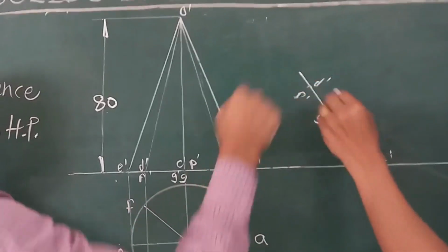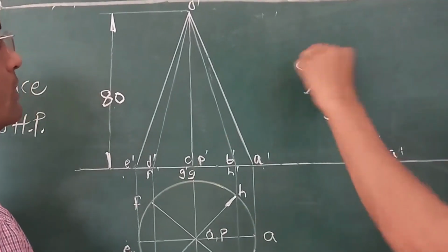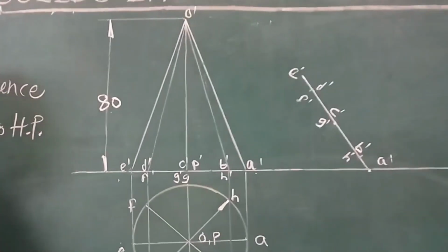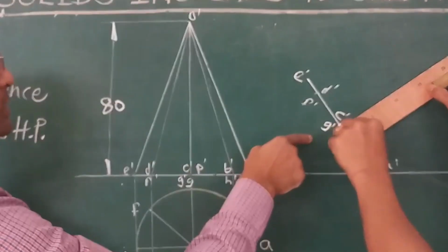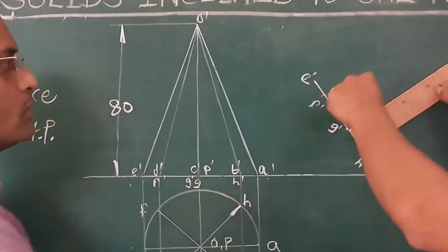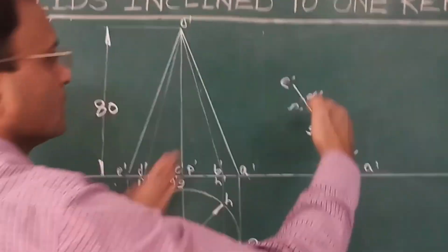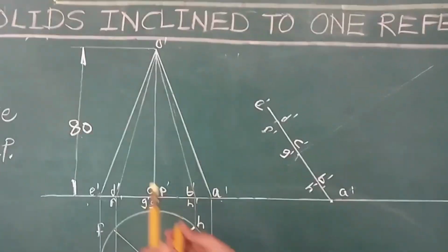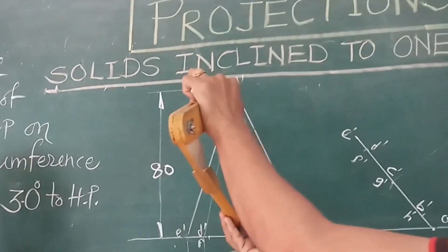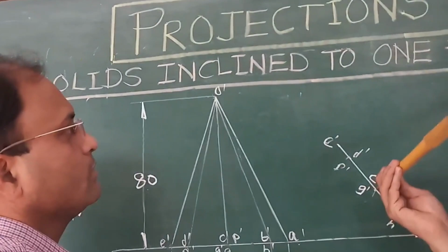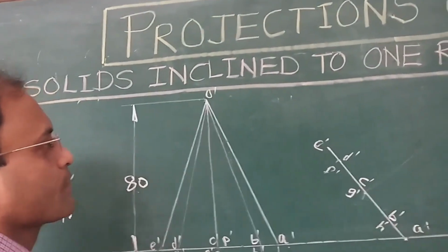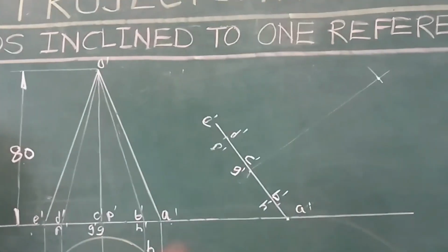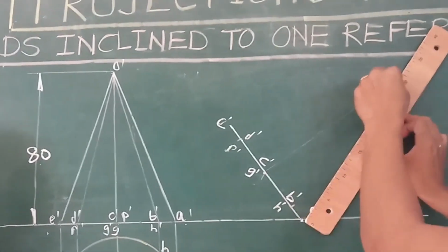This is extreme point V dash, point 1, and now this is also point P dash. So through this, draw a line perpendicular to base. To this base we have drawn one line perpendicular, which is the axis. So along this line mark height of axis, and now join apex with all the base points.